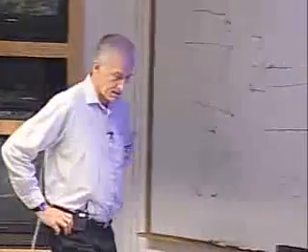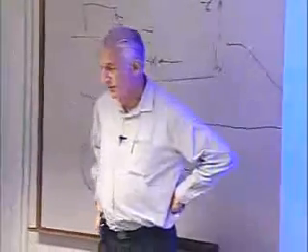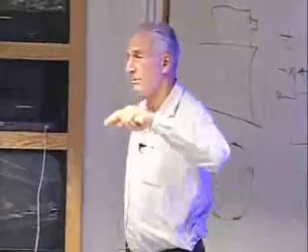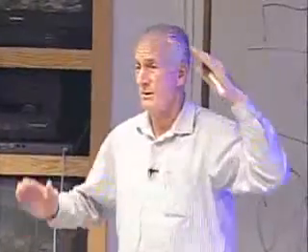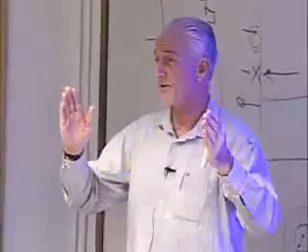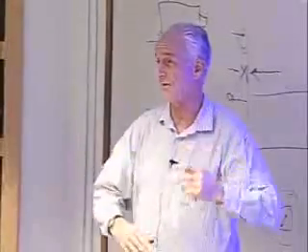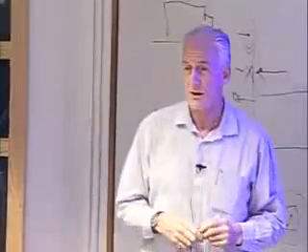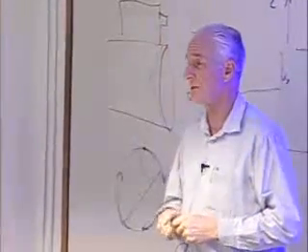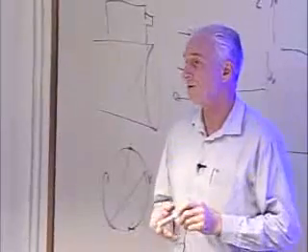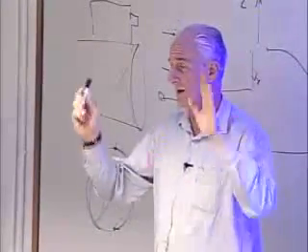Okay, so yeah. This is a ways back, but how noticeable are the big changes in acceleration during, like, SRB separation or MECO? Okay, SRB separation, as I said, right before SRB tail off, F equals ma, and the force is pretty much constant at that point, but the mass is decreasing because you're burning a ton of fuel, over a ton per second. So the acceleration is increasing, and you've built up to about 2.5 Gs when the SRBs finally tail off and you get rid of them.